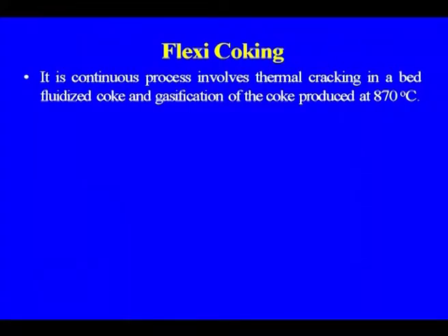Another development in case of the coking process is flexicoking. It is a continuous process which involves the thermal cracking in a fluidized coke bed and gasification of the coke produced at 870 degrees centigrade. So, this is flexicoking.